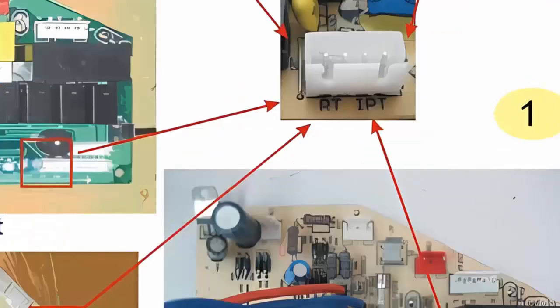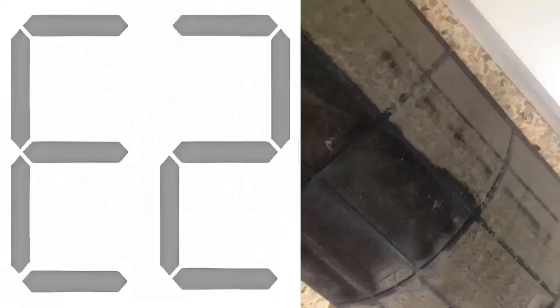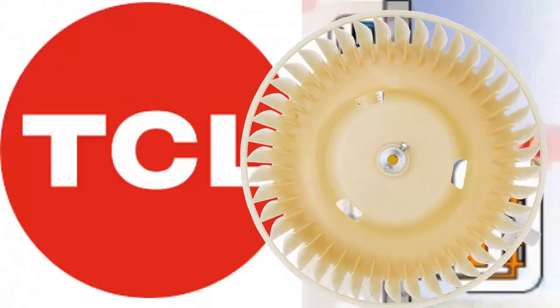4. Check the cleanliness of the turbine and air filter in the indoor unit to ensure the unit is in optimal condition. Remember to visually check the proper rotation of the fan. With the unit turned off, make sure the fan turbine rotates freely to rule out mechanical issues with the fan.